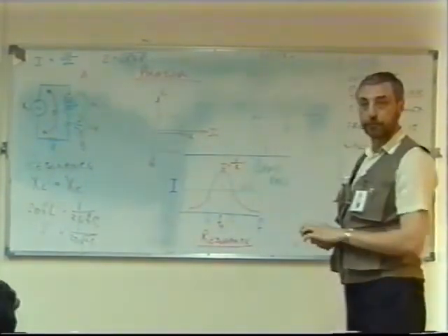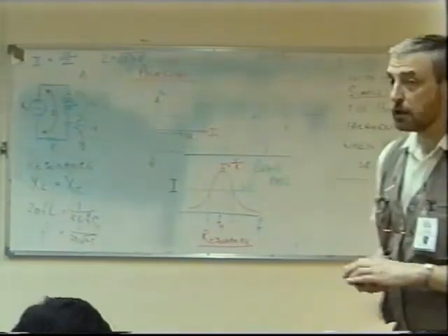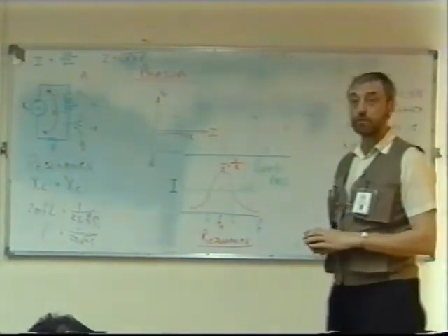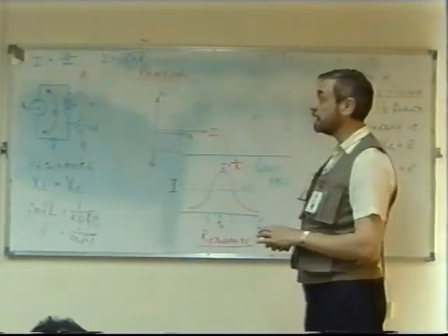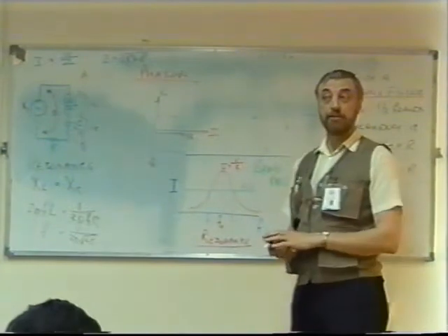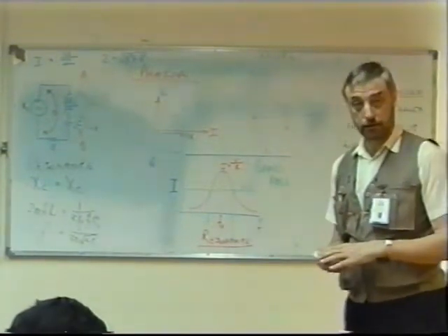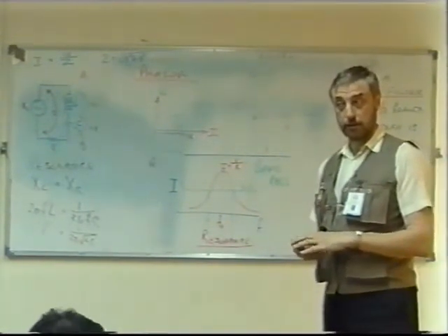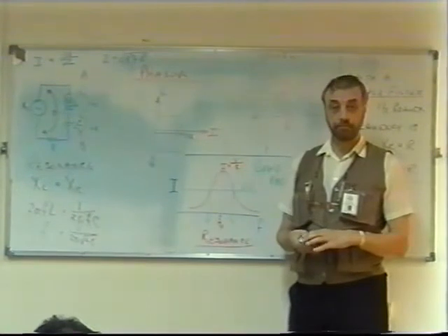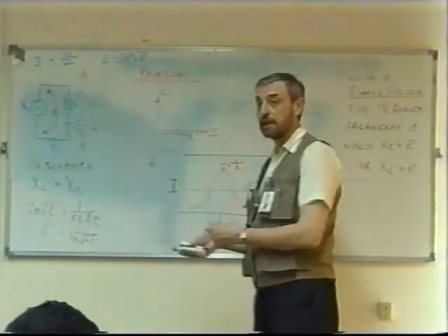Is it commonly called a bandpass filter or just a tuned circuit? Just to keep it simple, this is a tuned circuit, there's no doubt about it, but here we're using this tuned circuit as a bandpass filter. There are different ways in which you can use a tuned circuit. Another example is in an oscillator. But here, it's just the way we're using it as a bandpass filter.